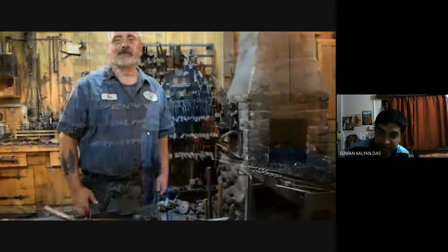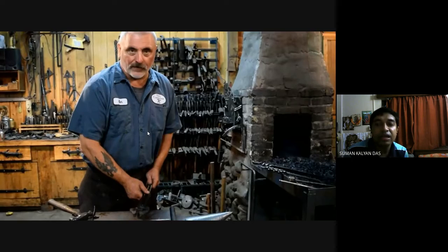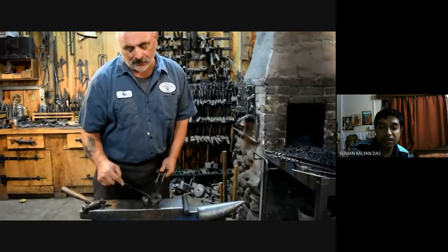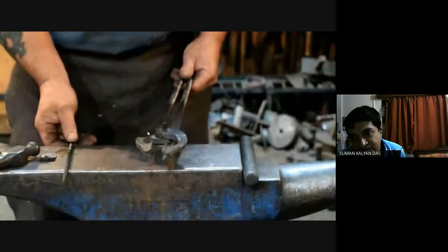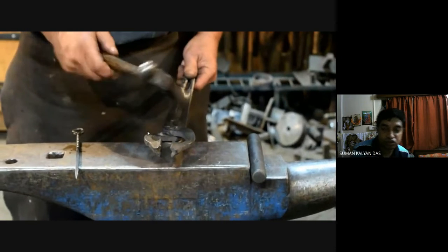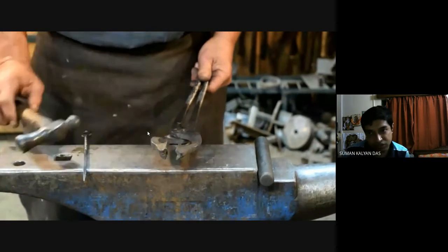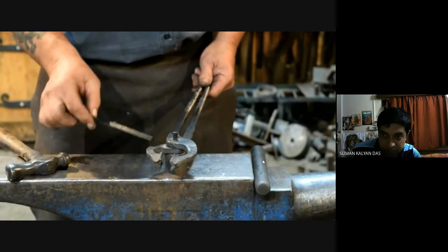However, again, as a general thumb rule, please understand that the rivet material and the base material are normally the same. If you are using two mild steel plates to join, please use a mild steel rivet. If you are using two aluminum plates for joining, please use aluminum rivets. If you are using copper plates to join, please use copper rivets. Got my point? Yes, sir. Okay.